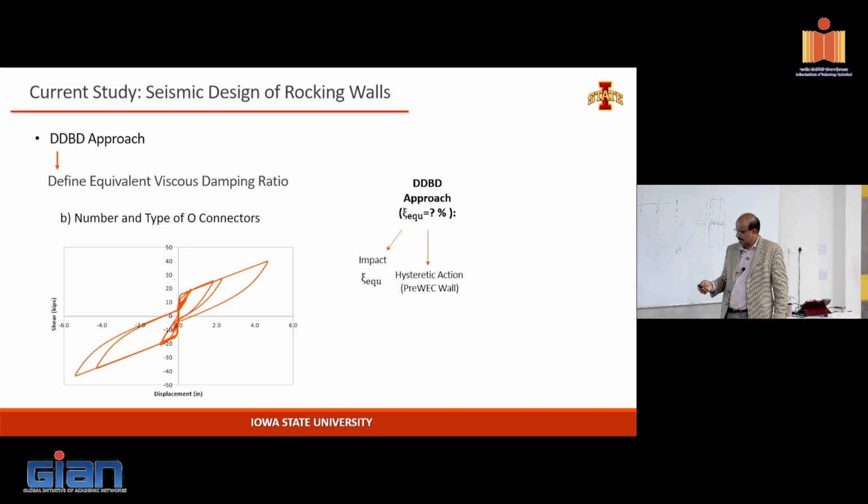So we're saying that if this value is 25%, maybe it's 30% of this peak value. If you come straight down, you're basically retaining a permanent displacement of almost 100%. So if this value is reduced within some numbers, then we believe that recentering will be achieved. So we introduced a jointed system, we promoted the idea: no damage, recentering, minimize damping.